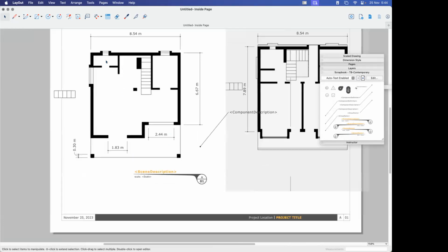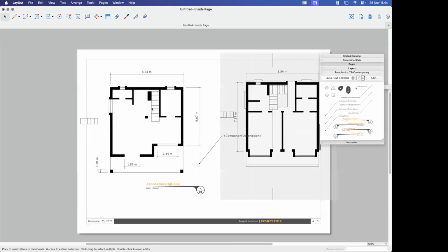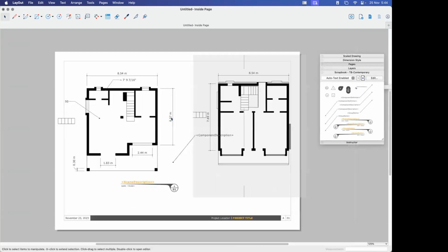Also, one more thing is if you have named and saved them as components in SketchUp, and you directly have a name for the component, you can use the option here, and it is going to directly label what your component says. So you don't have to manually type anything here. If your component says 5 or 50, it will just mention 50 here. Right now, we have not named any components, so it wouldn't take directly.